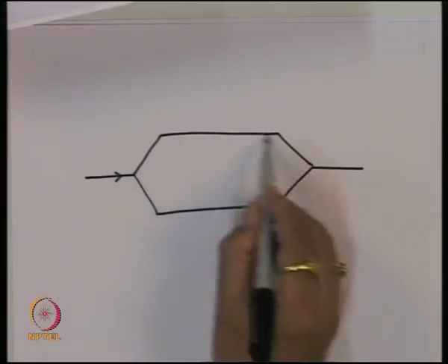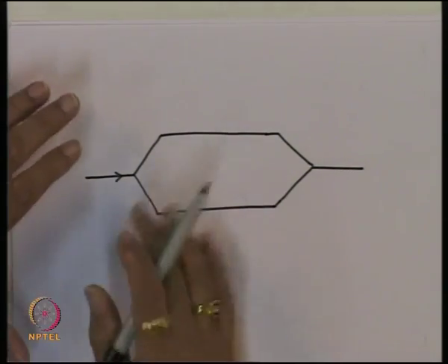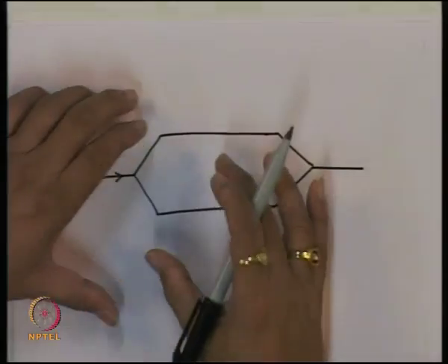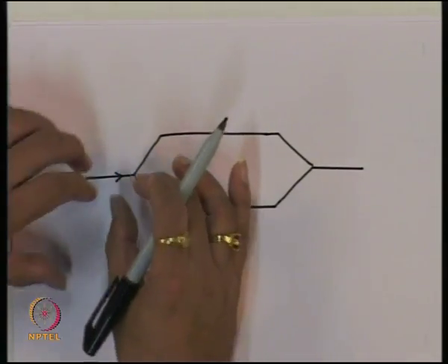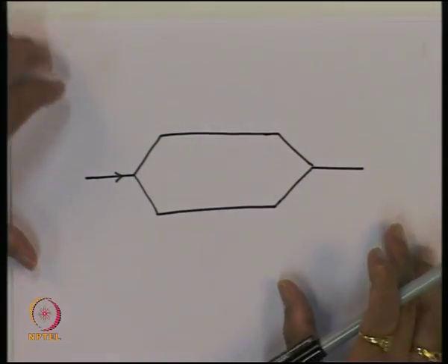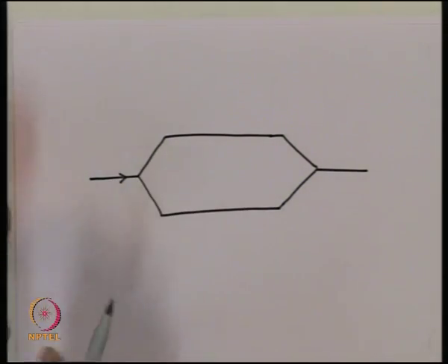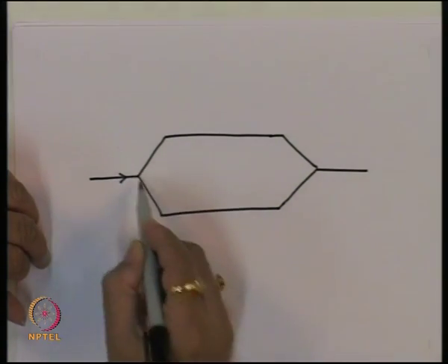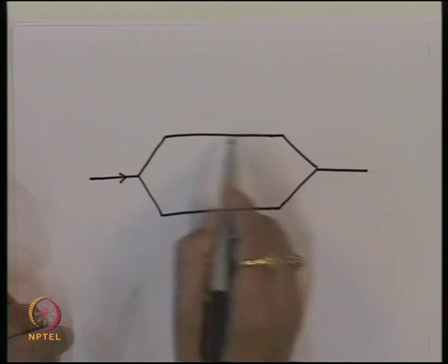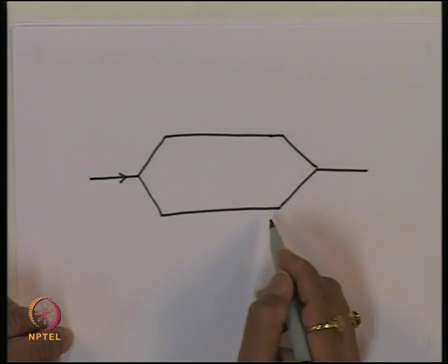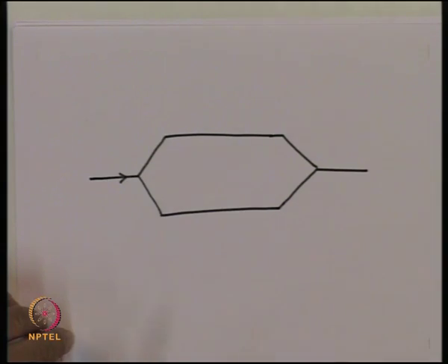One of the things on here is like a phase modulator. So you have a substrate here which is lithium niobate, and on the lithium niobate you have created the channel waveguiding structure which will look like that. The light is brought here, you have a two-way power divider. So the light gets equally divided into these two parts. It propagates in these two arms, and again it combines here with an equal combiner, and you get the light out.